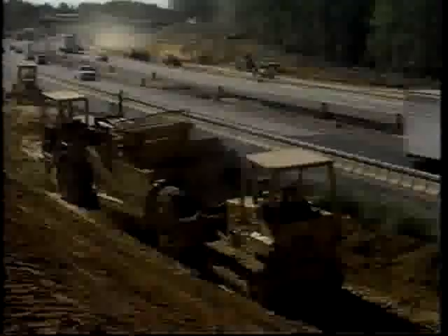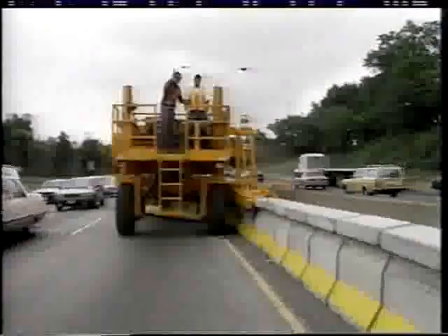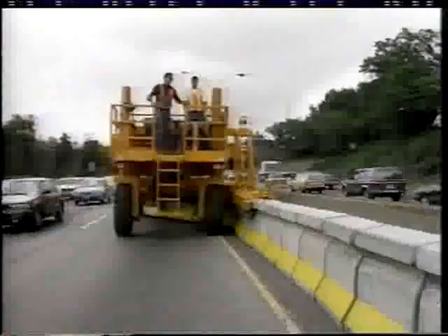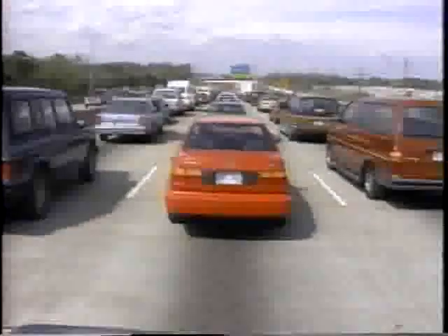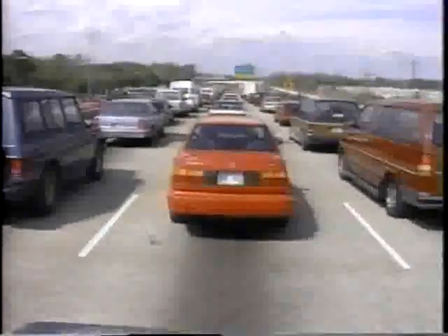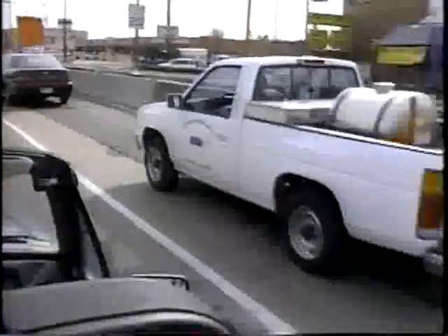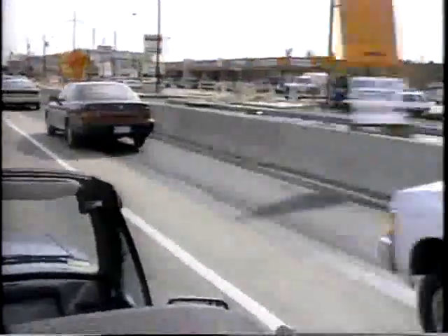The QMB can be used to open and close work areas on shoulders or medians. Because of their size, smaller and less intrusive equipment can be used during initial setup. Not until work is about to begin is the barrier moved out to close a lane. Consequently, the motoring public can be spared the frustration of passing by a work zone that is blocking a lane when there is no apparent work underway.